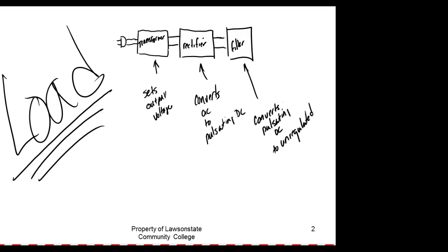If you're connecting a light bulb, or running a heater, or a DC motor, you don't need regulated voltage. So it all depends what load you're trying to run with your power supply. And of course, eventually we're going to get to a regulator, and then over here we'll have our regulated DC.